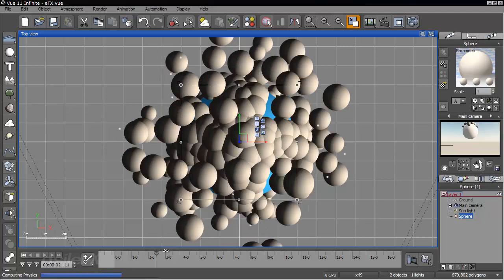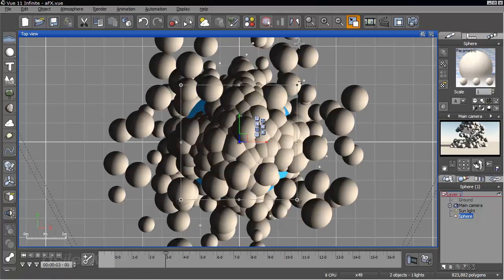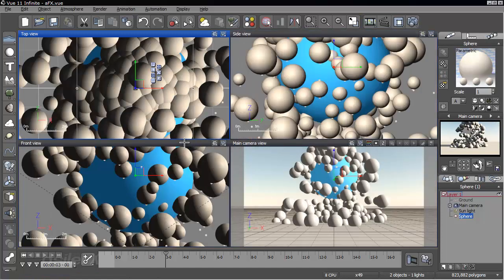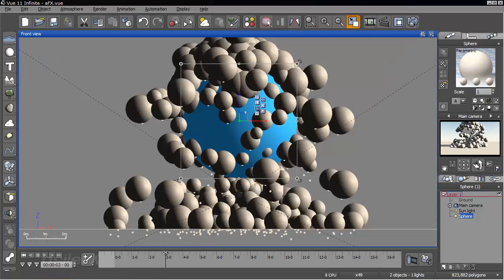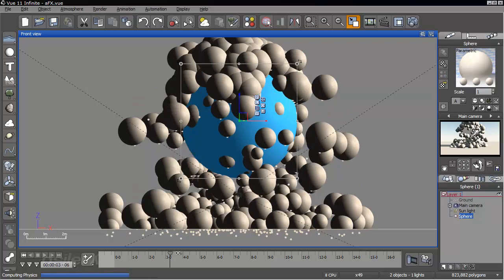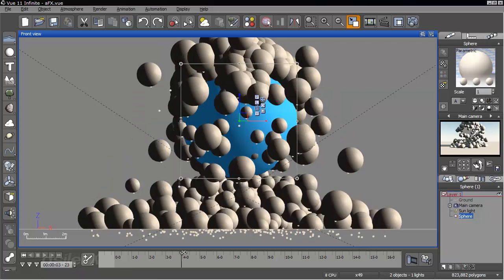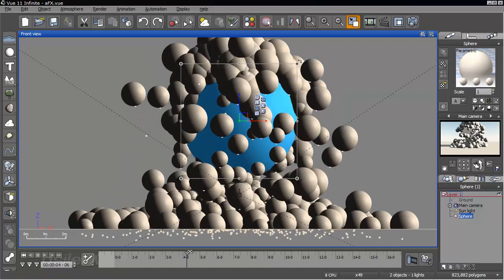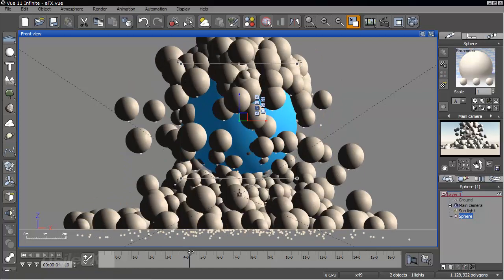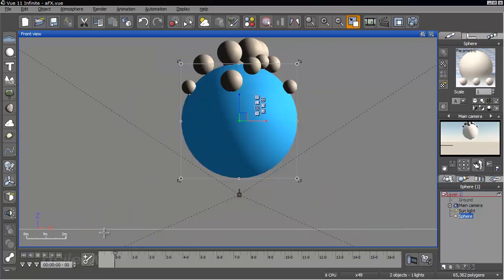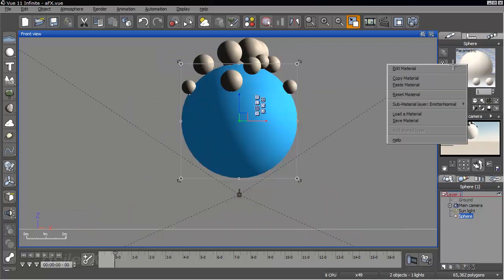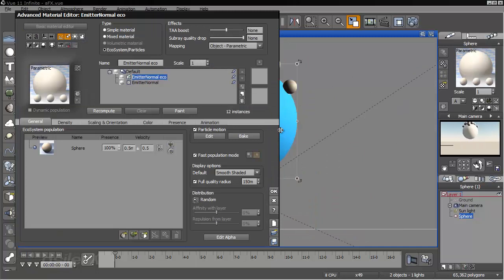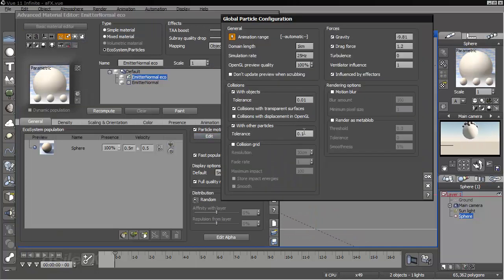And as we start to lower this value, it's going to take more time to calculate because we're now calculating the surface more accurately. So the lower the tolerance, the fewer intersections you're going to get, and something that's a little more accurate, although it does take longer to process and calculate that. I'm just going to go ahead and turn that off.